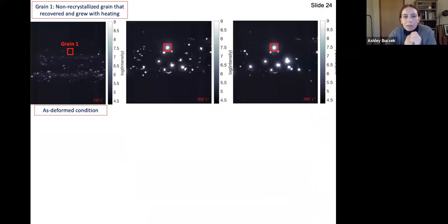The other thing that this partial HEDM technique is useful for is grain searching. When you're doing dark field, especially if you need to do some in situ work before you pick which grain you're going to do dark field on, so you can't do it ahead of time, this is a nice technique that you're probably, or John's probably doing anyway, so you might as well record the data. And that's what we used it for. We took measurements of the initial microstructure, but then we paused during this in situ heating process to pick out interesting grains to do dark field on.